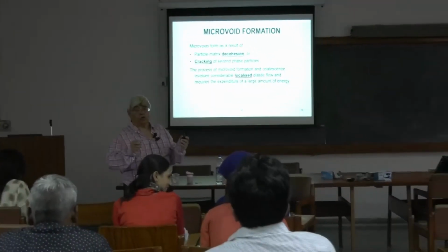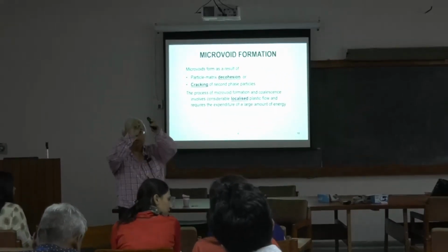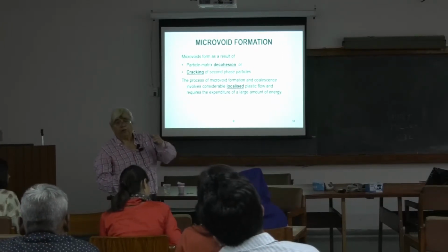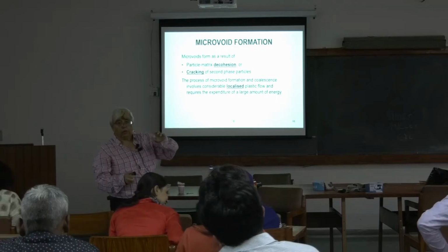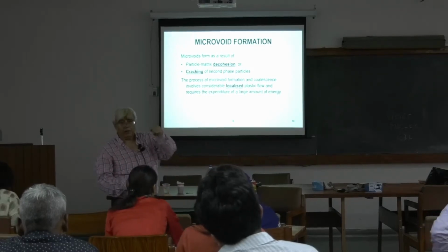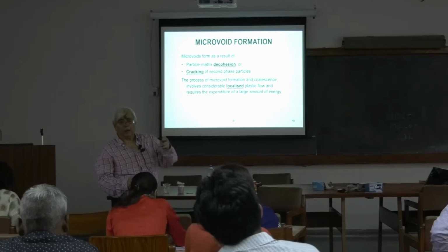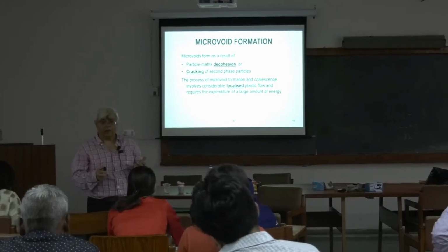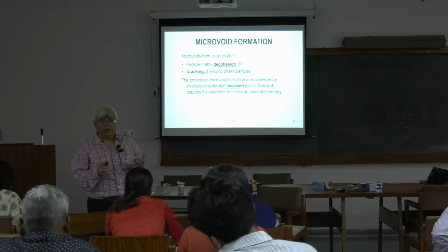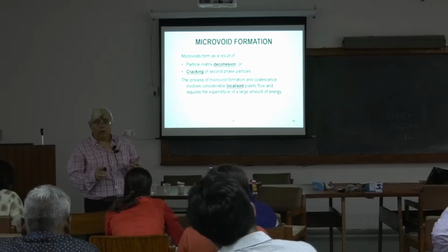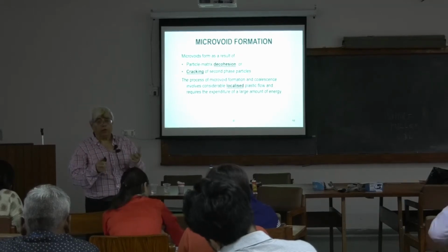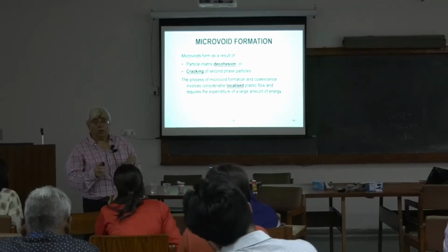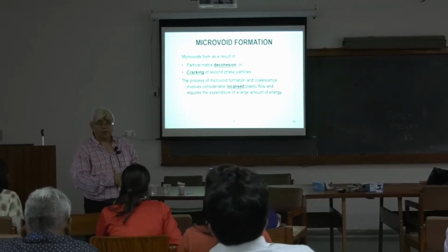What is short milled carbon fiber? They take it from any composites industry which has carbon fibers, and the waste material, a lot of carbon fiber fabric, is considered waste and thrown away. So they say, don't throw it away. They cut it into small pieces, and they shred it. It's like a modified carbon fiber. Carbon fiber is much more expensive, and this is like another waste material, short milled carbon fiber. But when we put it there, it shows that it's not an ordinary material. It is low cost, but it can be a very toughened material.